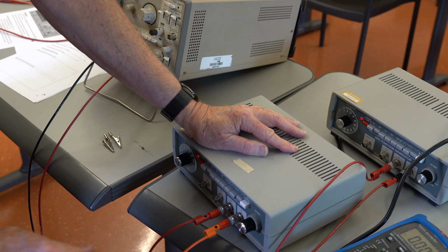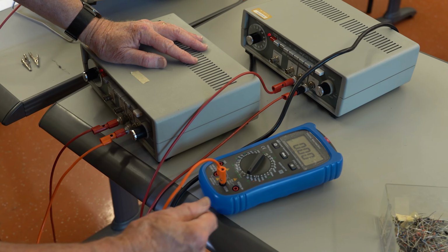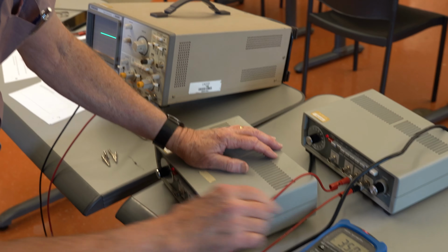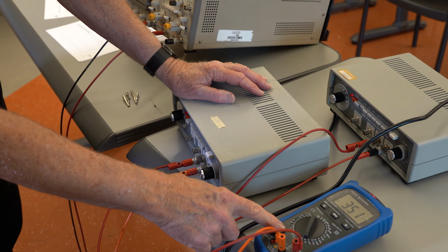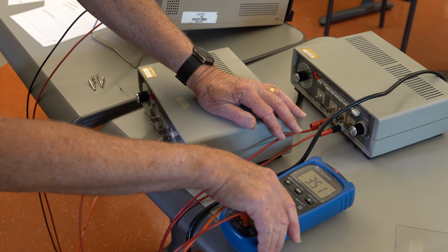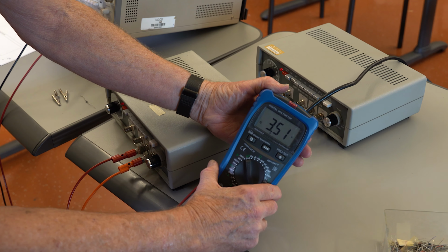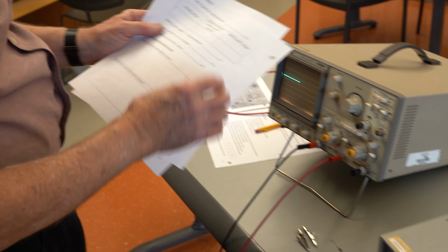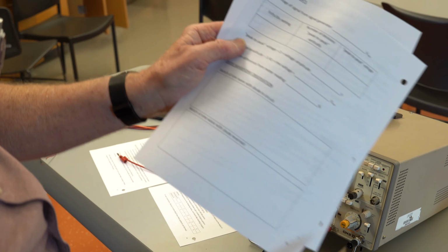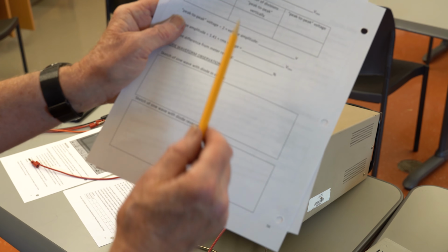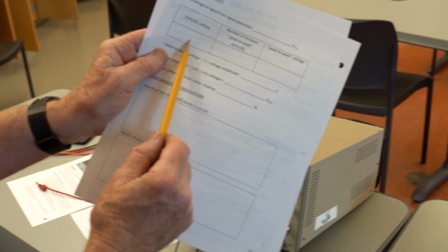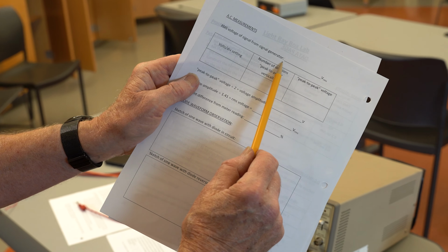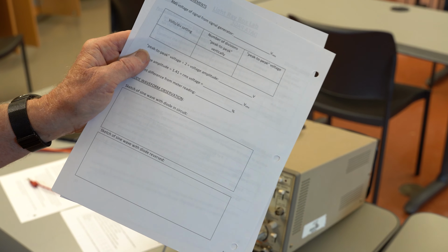Now this is the RMS voltage reading. The root mean squared, in other words, it's a sine wave, but this is measuring the sort of average of the voltage coming out, and we're getting 3.51 volts RMS coming out of the frequency generator. That's the number that you should write on your data page, AC measurements, page 56. You should write 3.51 volts right up here where it says VRMS, the RMS voltage signal coming from the signal generator. So now we know what that voltage is.